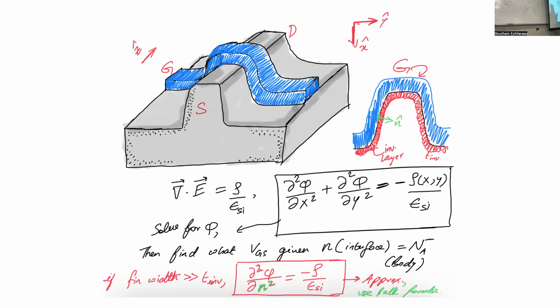So it's very important to understand three-dimensionally how the FinFET is, right? In this case, this is the source and drain, and these regions are going to be the silicon germanium. And if I was to draw the same thing over here, this would be like this, and go like this, and then like this. Understand? In that plane, right? And so this will be the lightly doped region, and then this whole piece will be replaced with silicon germanium. That's your N plus, right? Yeah.